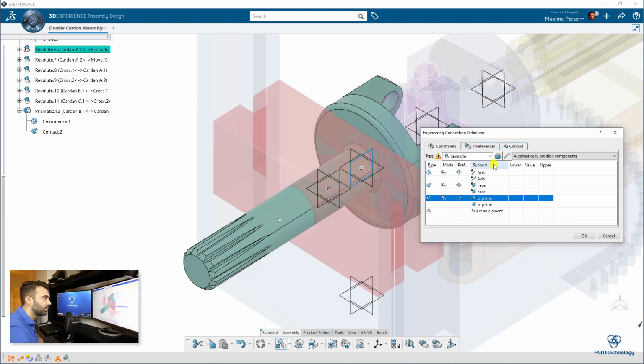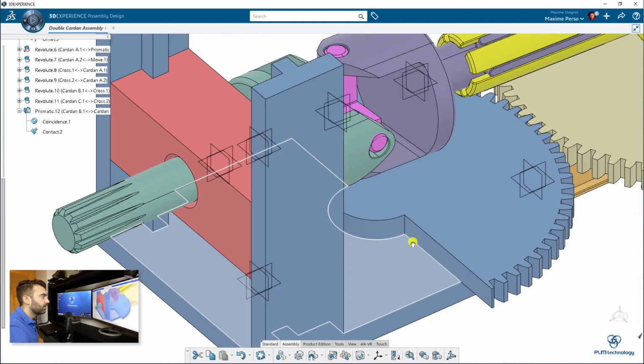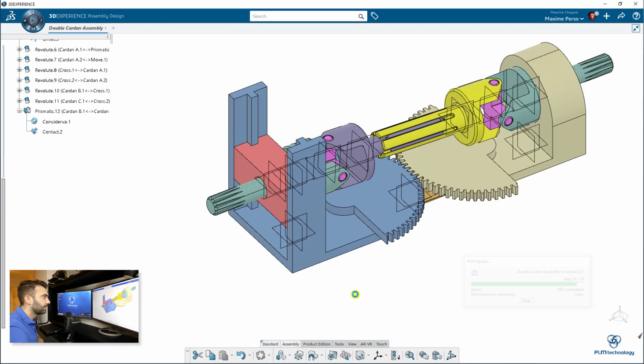Yes, I want to enrich my Revolute. Remember, we replace to angle, we change that to control, so then we are going back to prismatic, to Revolute, and I put 0 degree. I do not put any lower or upper value because it's going to be an engine, so it's going to rotate 100%. Click on OK, I update, and the first part of the video is over.